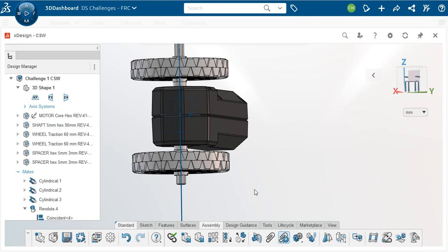from falling out. So let me grab the axle and let me move the axle and see how the axle moves back and forth. It would be terrible if you had a robot and your axle fell out. Okay? Matter of fact, they have. We've seen them. And so what we're going to do now is we're going to use another device called a collar that will fix the axles onto here. So let's pick up a collar.